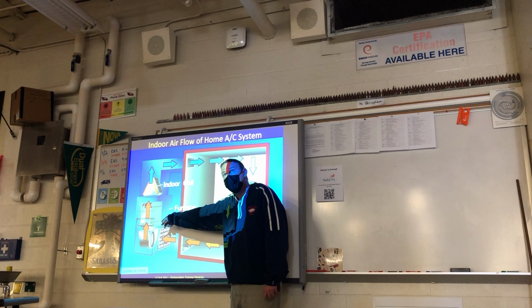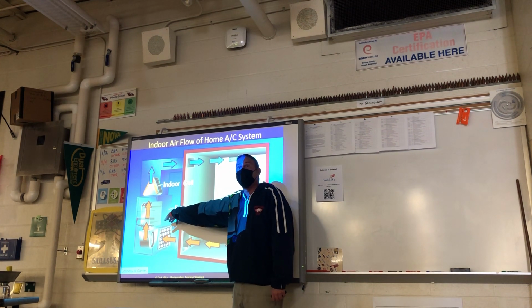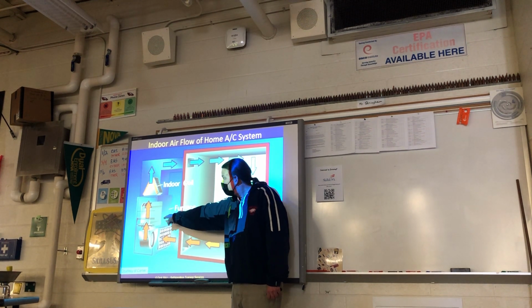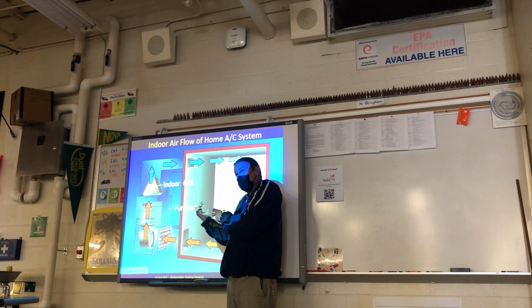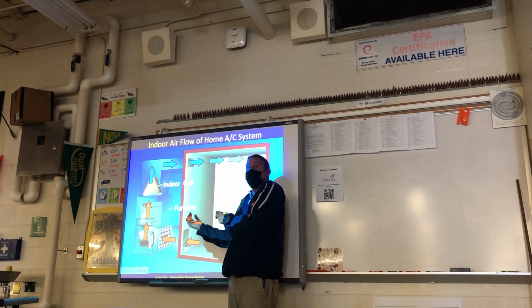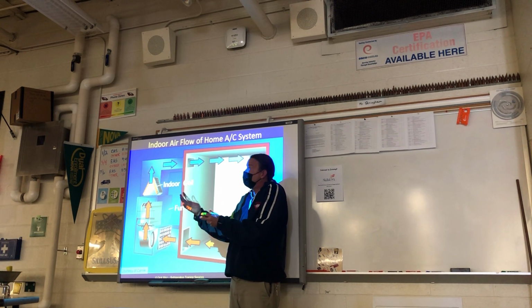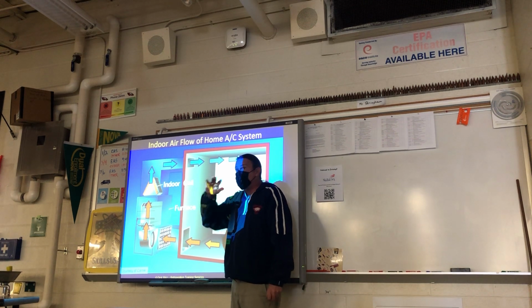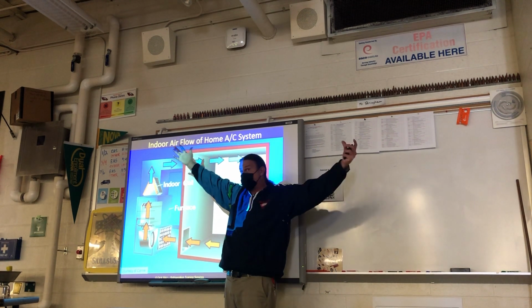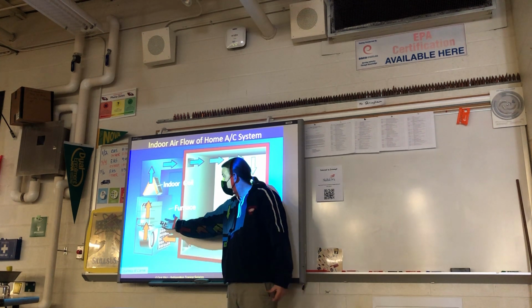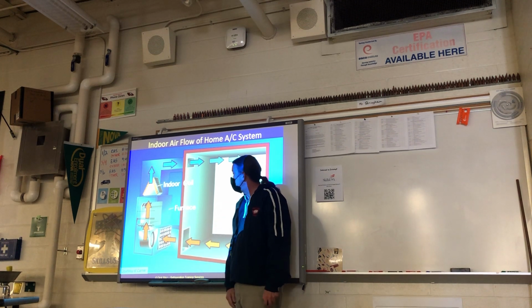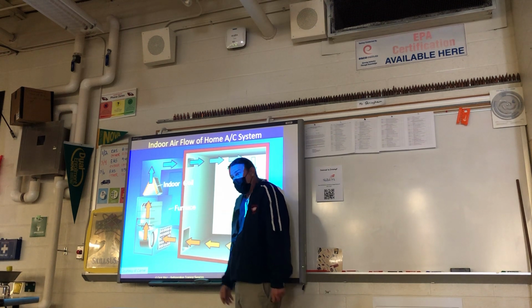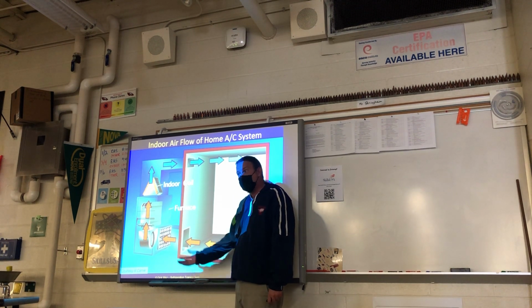Because that is a big one. There's a little tiny flame sensor that keeps the unit from coming on, and the unit will fire off. I'll show you this a little later, but it builds up with some carbon, and the sensor doesn't read the flame, so it doesn't think there's a flame on. They can't have the gas valve open if there's no flame, because then the whole house would fill up with smoke. So they shut it down, and that sensor confuses the board, even though it's on and running, into thinking it doesn't have flame. So they end up sanding it, cleaning it, and then it worked just fine. Fired right up, stayed on, customer was happy.